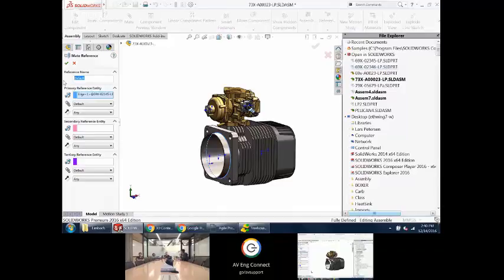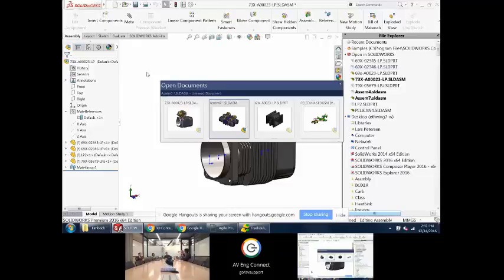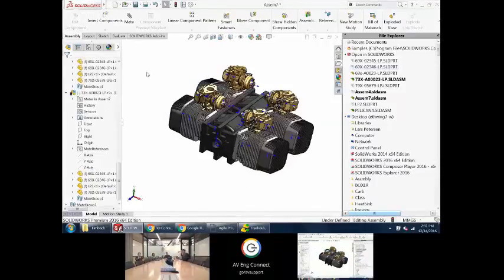I can be stupid and smart at the same time. Yeah. Just a rudimentary smart mate, I should say, because you can get really complex with them if you name them. It's got to have a matching face on the other end for it to work. So if you name it, you can separate, like if you have circular edges that are different sizes, you can more or less filter them with the name. Yeah. And we can take that into another thing because you can go a step beyond that.